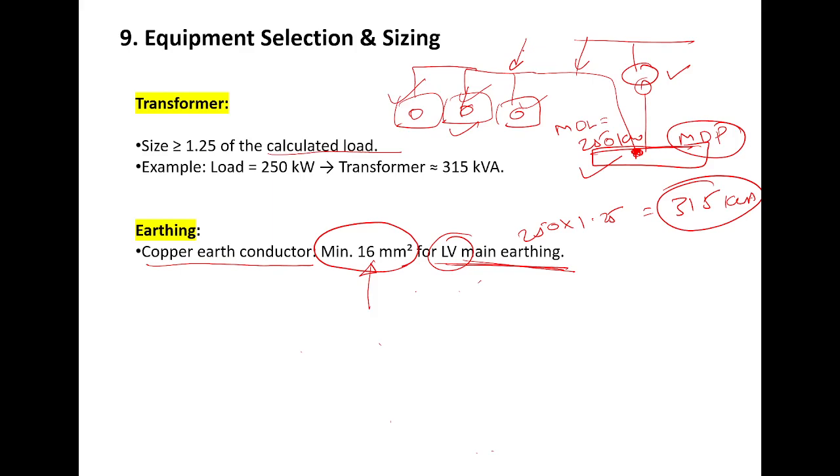He just had a meeting with the client without any information. The only information was that we have 3 floors in the building, and each floor has 300 square meter area. So based on that value, I used these rules of thumb, created my SLD and shared it with the client.